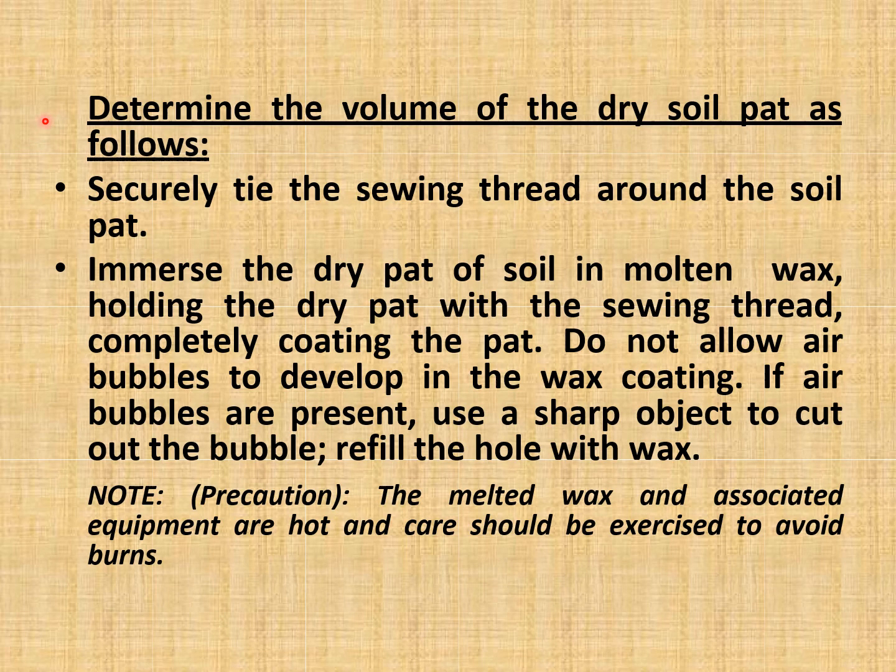Determine the volume of the dry soil pad as follows. So this point is very important. Securely tie the sewing thread around the soil pad. Immerse the dry pad of soil in molten wax, holding the dry pad with the sewing thread, completely coating the pad. Do not allow air bubbles to develop in the wax coating. If air bubbles are present, use a sharp object to cut out the bubble. Refill the hole with wax.